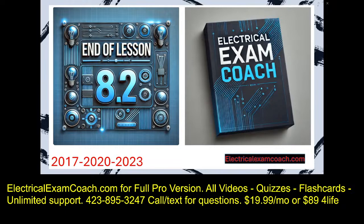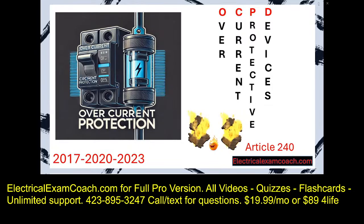Let's get to it. Hey everyone, welcome back. I am the Electrical Code Coach from electricalexamcoach.com, and this is lesson 8.3 in our video series. We're still in Article 240, but we're going to be doing sample calculations of whole homes and businesses and selecting the main overcurrent device. Learning how to take all the work that we've done in the program up until this point, the load calculations and everything, and then take those total VAs and find out how to choose that overcurrent device, which will ultimately dictate the size of the service.